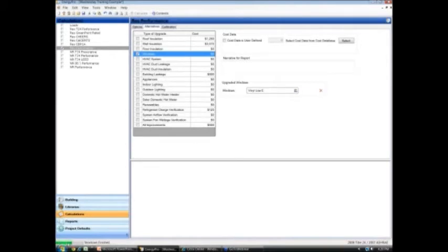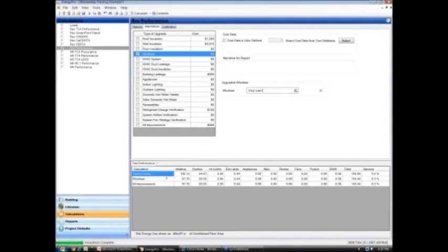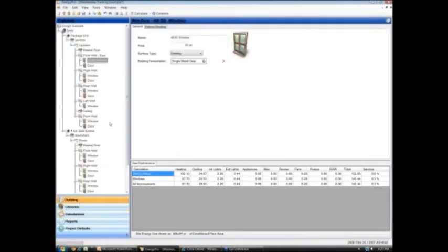It's going through and doing the calculations right now. It's showing me that if I replace the windows, it gives me a 6.3% improvement, and it just replaced every window. Now, this window right here that I've labeled 4050 is actually a stained glass window that my grandmother installed in the house. You can put in vinyl low-E windows everywhere else, but you ain't touching that window. I've got to have that window.